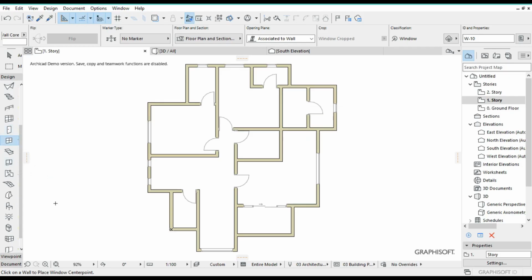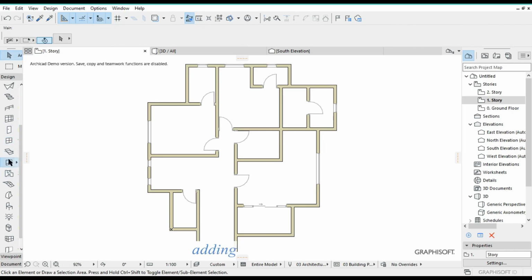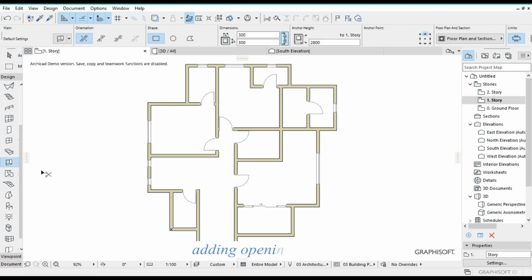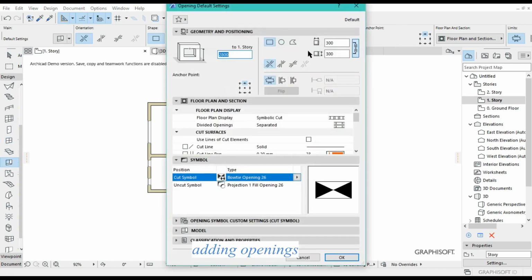To place openings, we are going to use this tool, Control T, then mark that and check that. This is where you adjust your length. The first one is going to be 3400, the height will be 2550, but to store it, this one will be 2400.